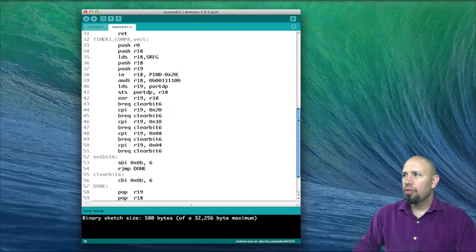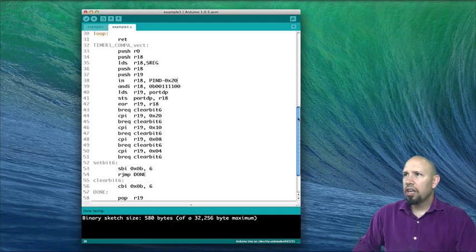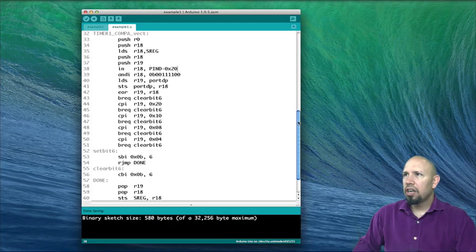Okay, so here is our interrupt service routine vector as our label. And so the first thing I do in this function is I want to save whatever may be used by this function so that I can return it back to the original state when I'm done. So this is very important to do in an interrupt service routine. It's very important to save whatever variables you use.